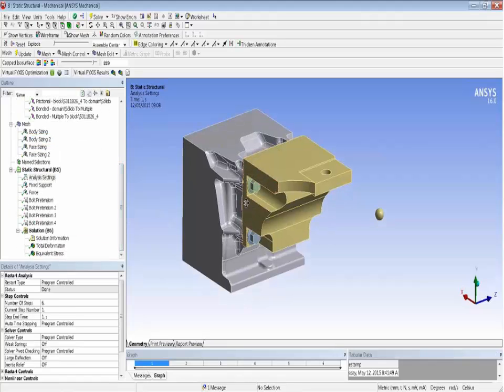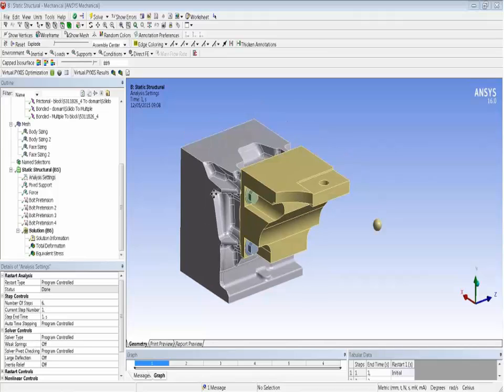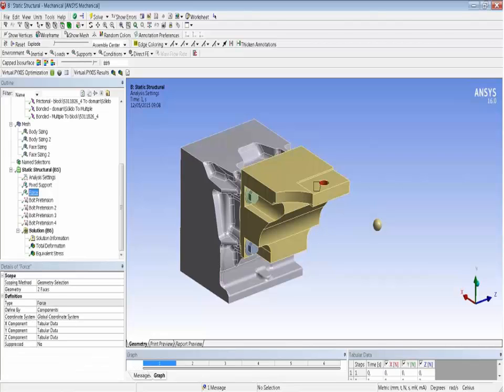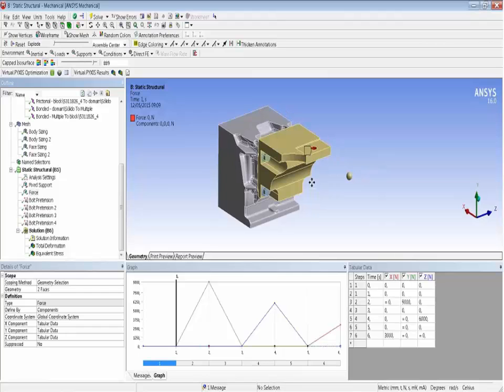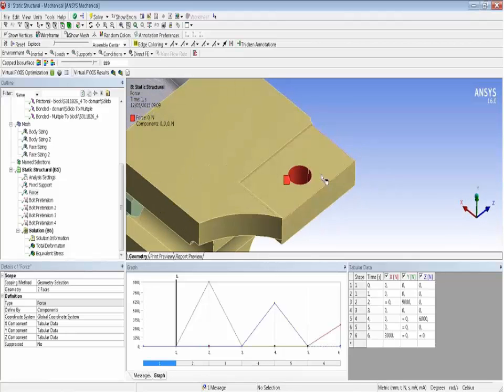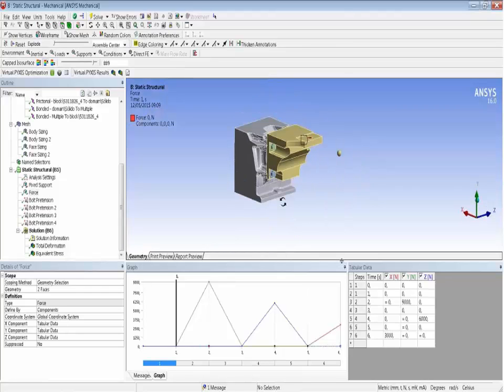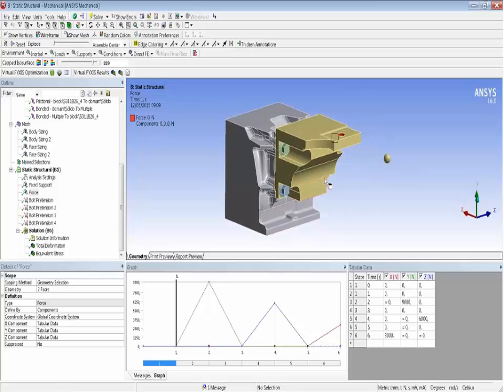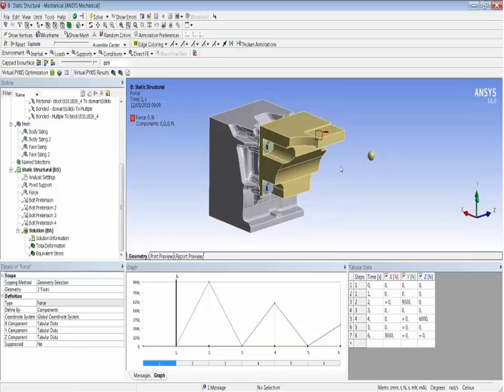Now let's talk about the load steps. We have 6 load steps, and the force for these load steps is applied around this hole, the red region here. Those 6 steps are real forces, for example in the X, Y, and Z directions, representing conditions of the engine during application. You have a lot of different conditions, and for different directions you have to account for these forces in the optimization.